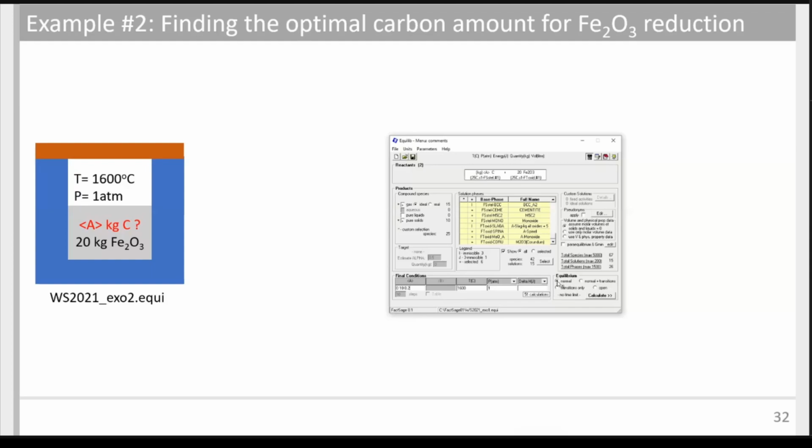I can keep this normal option, or I can add the option of normal transition. In this case, the software will try to identify the alpha value at which specific phase transitions are occurring. So I'll try to use this option as well. There will potentially be more than 51 calculations, as the algorithm finds some special values of alpha associated with first-order transitions.